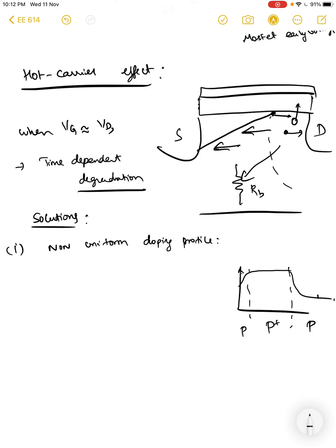But this is a typical doping profile that is employed to avoid short channel effects where you have source drain charge sharing, right? To reduce the source drain charge sharing, you increase the substrate doping, and that's what you do here. But if you do something like this, you have to reduce it here to avoid base effects, but then this will cause subsurface punch through, right? So basically you have to work around with this profile to give you the optimum solution.